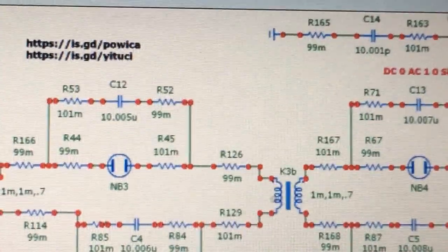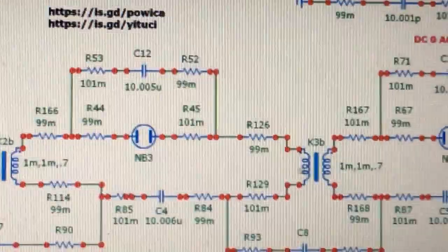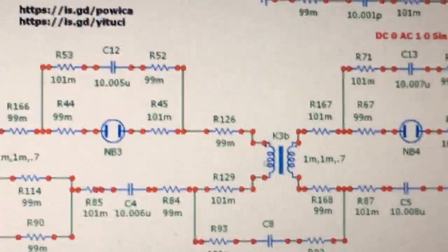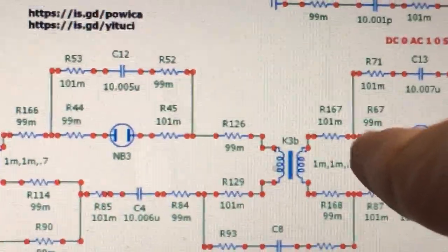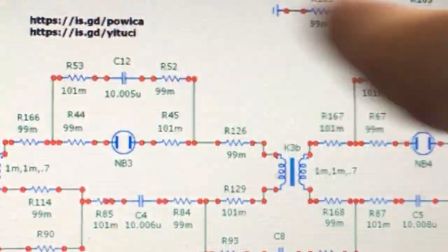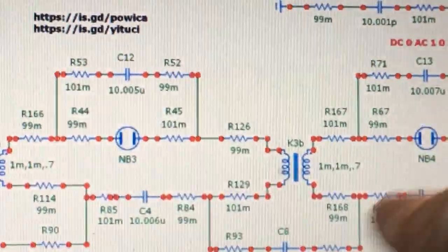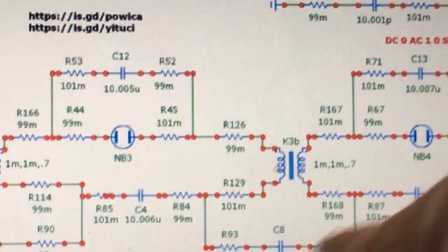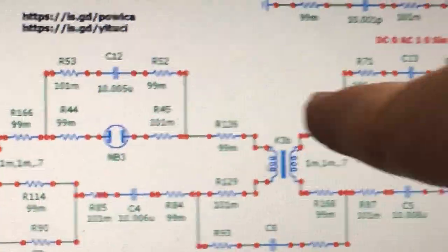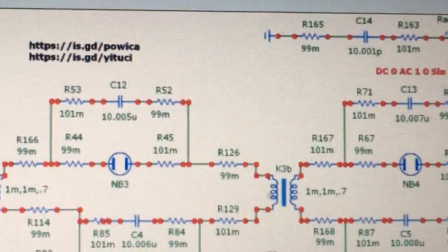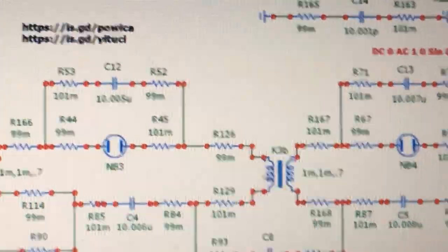And so what I'm finding is I don't need any switches to basically build this thing, to make it run. I just need a switch to regulate the output. Now, I used to say that if you reduce the mutual inductance, you'd control this thing. But that was in LTSpice, and I may not have had these shorting capacitors underneath the transformer. And in LTSpice, I couldn't control it at all. It just blew up in my face.